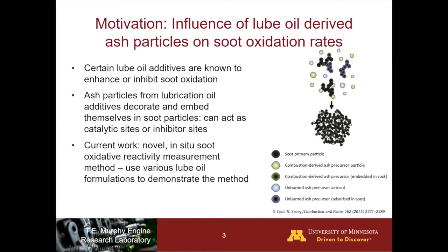In the top picture, you have free-floating suspended particles, and then once those particles combine and are loaded onto the filter, they compact, and you can see the green dots are what you can imagine are ash particles interacting with the primary particles of the soot agglomerates. So in this work, we developed a novel method for looking at oxidative reactivity of soot using various lube oil formulations to induce different soot reactivity to demonstrate the method.